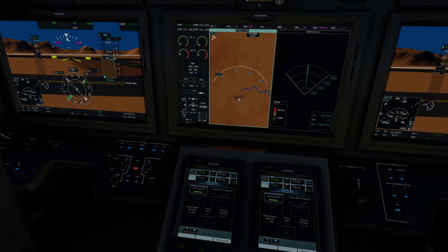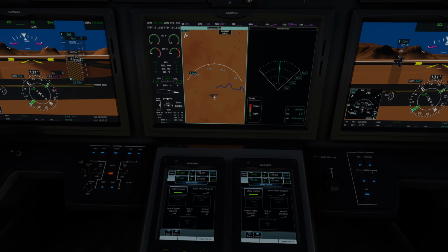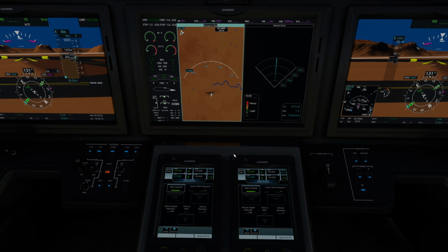And if you've flown on an airline or anything else, obviously when they start descending, it's almost impossible for you to really tell that that's actually happening. And that's because they're descending at such a low angle and on a vertical navigation descent pattern to where it descends like it's supposed to and keeps everything perfect and all of that. So again, right now this is just advisory vertical navigation. So you do have to do a little extra work. The plane's not going to do everything for you, but it definitely is extremely handy.